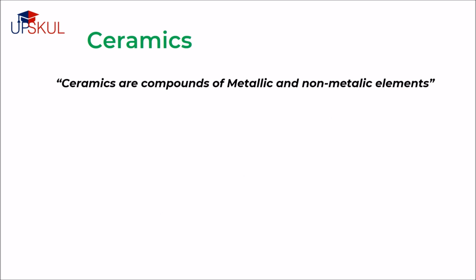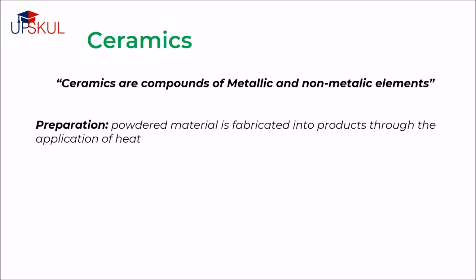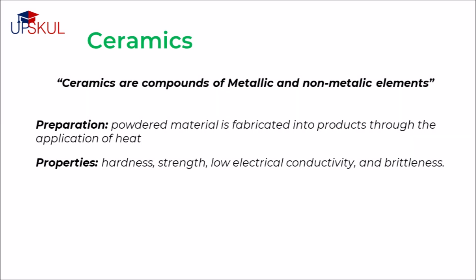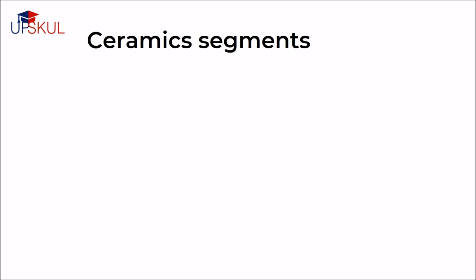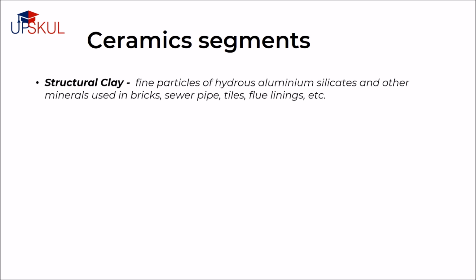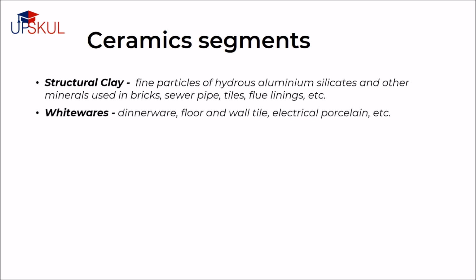They are prepared when powdered materials are fabricated into products through the application of heat and display properties such as hardness, strength, low electrical conductivity and brittleness. Ceramics can have different segments like structural clay, which consists of fine particles of hydrous aluminium silicates and other minerals. It is used in bricks, sewer pipes, tiles, and flue linings. Whiteware is another type of clay used in dinnerware, floor and wall tile, and electrical porcelain.